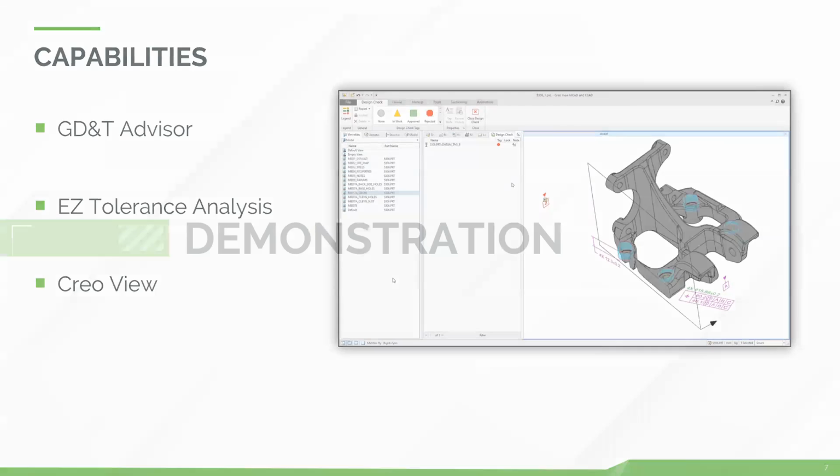All right, so I'm going to go through a demonstration and walk us through both parts of this. So first and foremost, we'll just speak a little bit more into model-based definition from within the context of our parametric environment, see some of the standard capabilities that we have in Creo. And after that, what I'll do is take a second step and we can look at the GD&T Advisor to see how it's going to help us in that process and how it's going to take something that might have been more error prone previously and really validate those models for us, help us to build out the correct annotations and help us to share the correct things downstream.